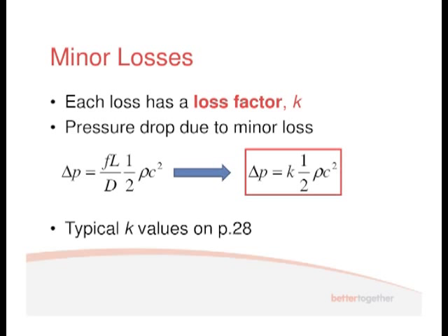Okay? Sorry about the quality, but we had to copy this from an old set of notes. And you can see we've got things like a section increase, okay, a section decrease. Then we've got an orifice, which you've all seen before, okay. We've got a taper, an enlarging taper or decreasing taper, a bend, a curved bend, various other sort of things as well, okay. And there are K factors. Sometimes it's just a value you pick. Sometimes you've got to determine it from different areas, okay.